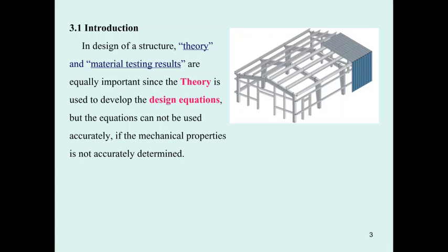That means if you want to be very reliable, you may need to use the mean minus 4 to minus 5 standard deviations to make your product so reliable. Okay, that is the concept of making the mechanical property of material reliable.